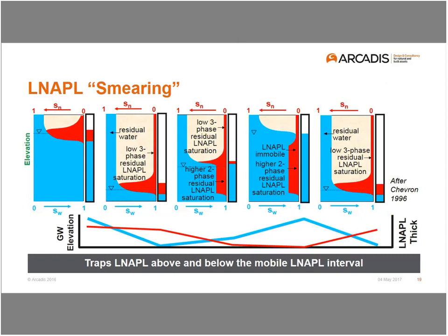So what else is going on? So you've got the LNAPL out there. It's formed a more or less stable body. Water tables move up and down. In some places a little, in some places quite a bit. So what's going on there is, here's a diagram showing how much of the pore space, again, the saturation, is occupied by these different phases. So here's the water table. Blue shows the water saturation going from 0 on the left to 1 on the right. And red shows the NAPL saturation going from 0 on the right to 1 on the left. And then this tan color is how much air is in the pore space.